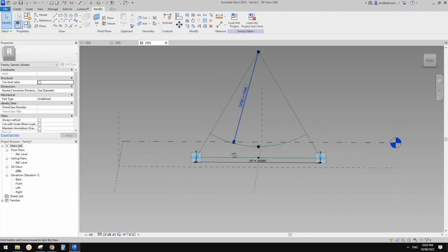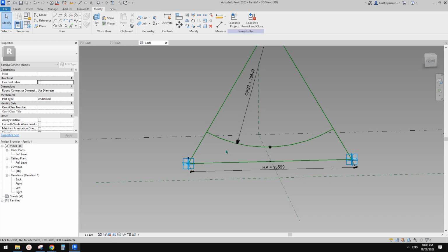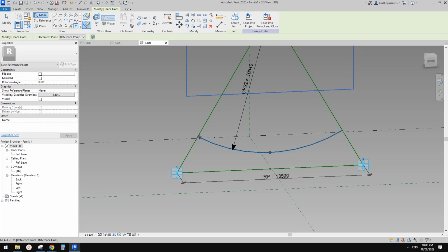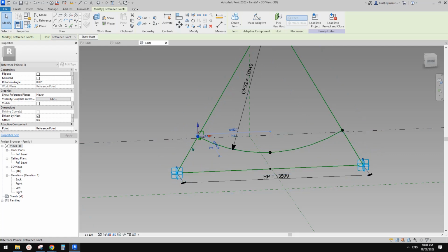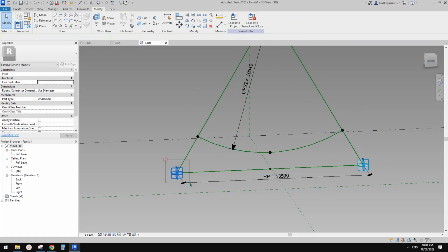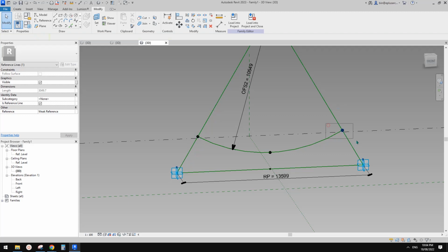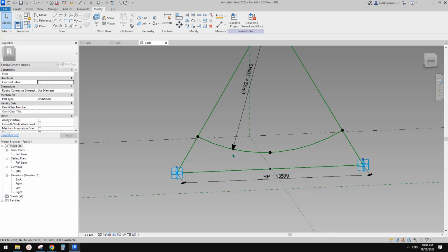So now you can see we have this shape, right? But it's still not enough, because I'll show you if I place a point here. So I'm going to place a point, use SE, snap end, and another one SE there, and because we want to create a profile, we need this reference line between these 2 points. Okay, and also this and this, and so we already have this. We have this closed profile, which is good.